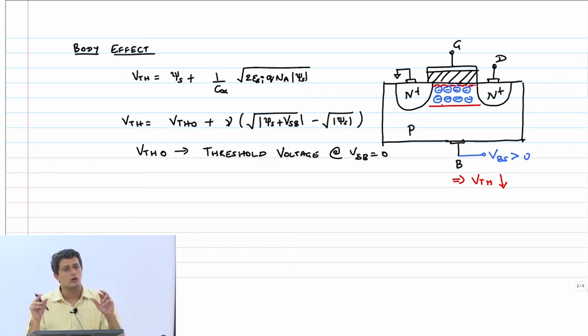So what we are doing is known as a compact model, which means that whenever it becomes very complicated or difficult to model something, you resort to an empirical model. So that parameter you will just fit. If I take the previous equation and scale oxide thickness Tox, I can guarantee that the threshold voltage will vary as per this equation. Now when I do this empirical fitting, if I change some parameter, there is no guarantee that it will work. It is very, very specific to what it has been fit to.